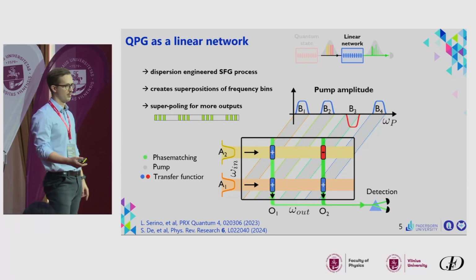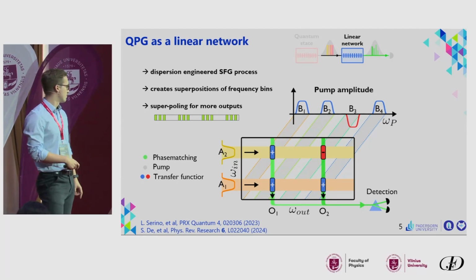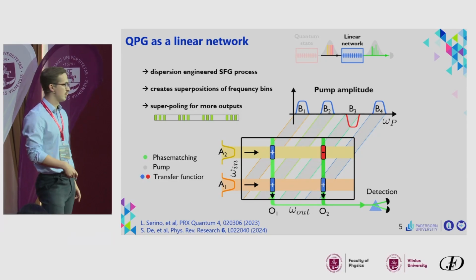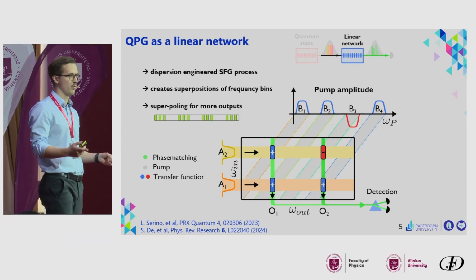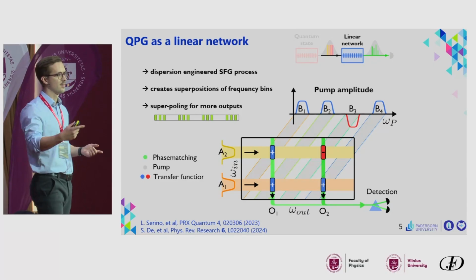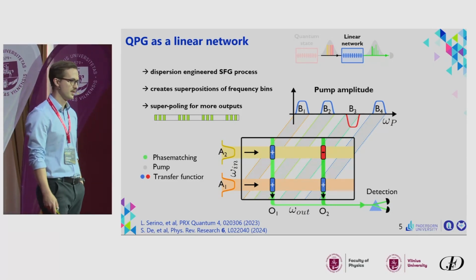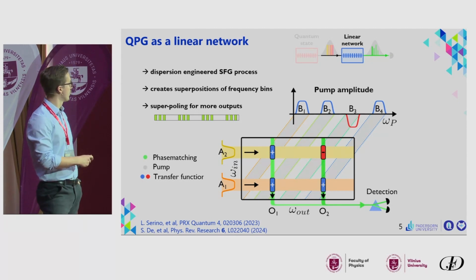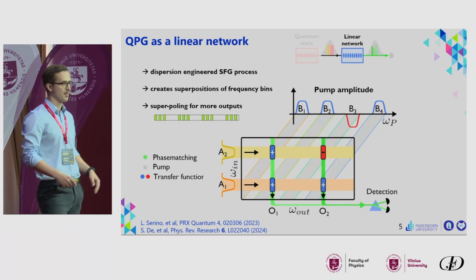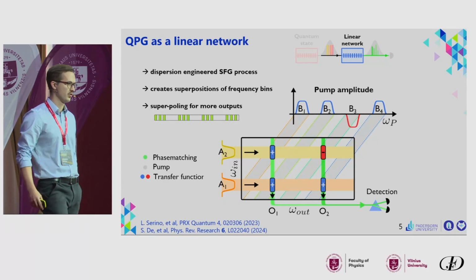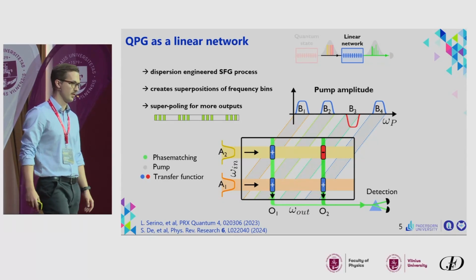And for the sample we used for this work, we just used the splitting into 2 output channels. But there's published work from our group in this paper, for example, where we have MQPGs published with up to 5 output channels, and there's no reason to not be able to go further in principle with that. You will hit a limit at some point because these patterns become quite complex, but it is possible to add more output channels simultaneously with that scheme, yeah.